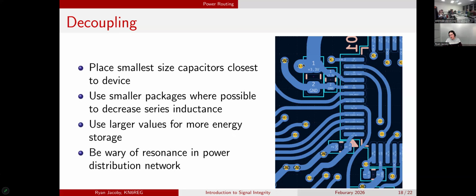But yeah, I was trying to route this across only 2 layers and having quite a difficult time with that. And similarly, there's another decoupling cap down here for this power input. And then, a couple ground vias, not as many as I would have liked to fit, but with the size, this was the best I could figure out. And then another one, we have another decoupling capacitor on this power input down here.